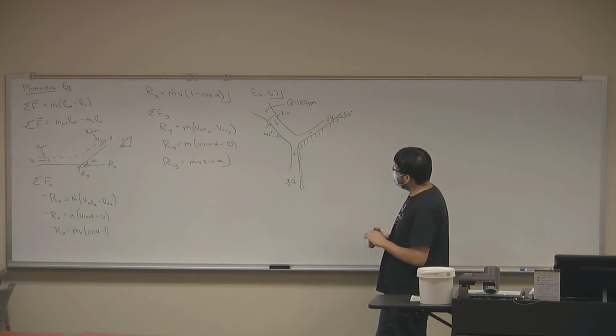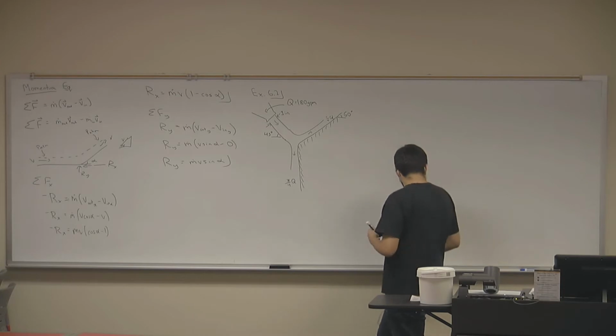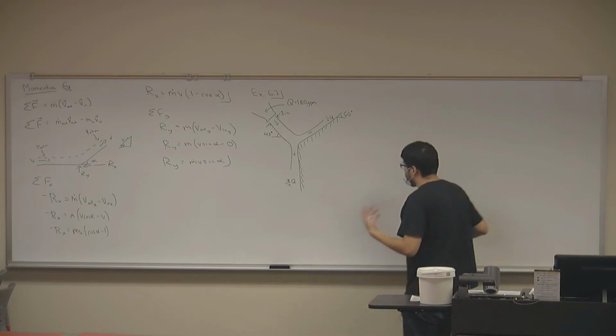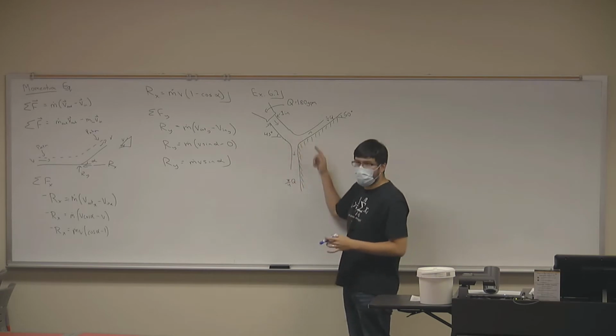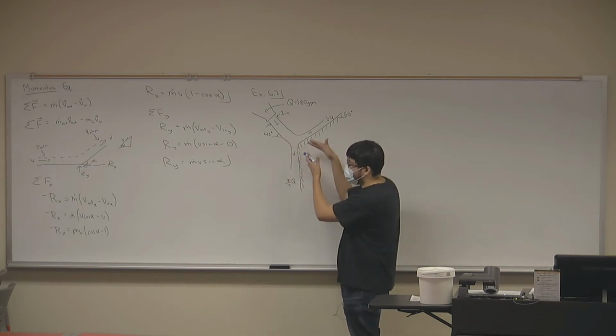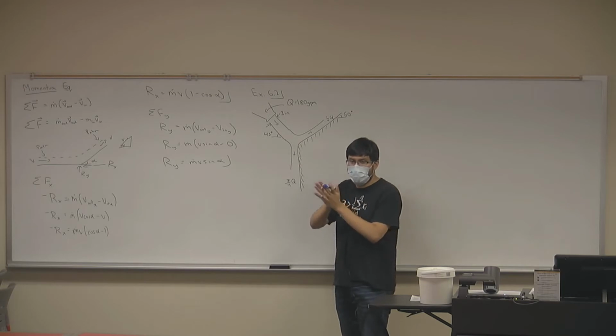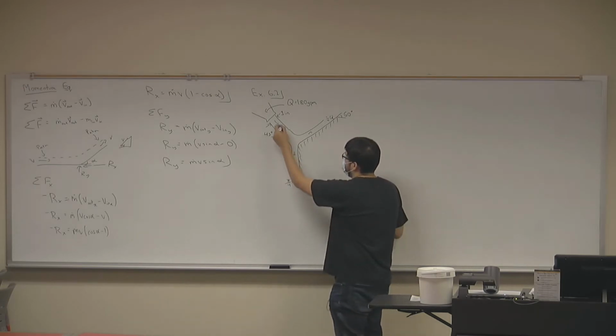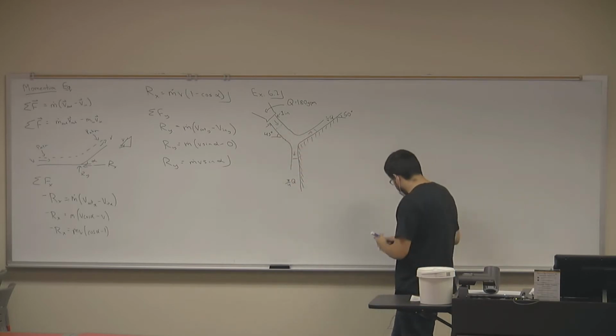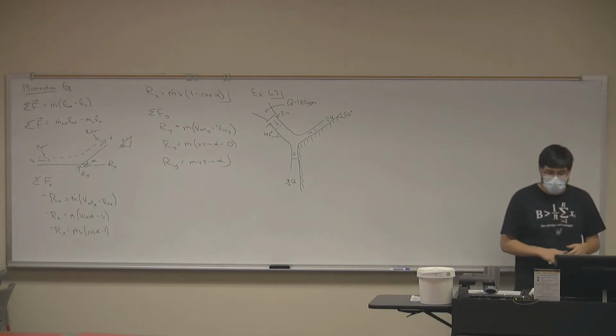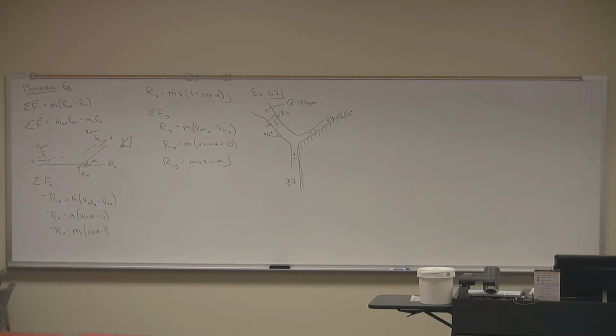We can select our control volume, and just by looking at the diagram, I would recommend that we select our control volume before the deflection, because then we can account for any exchange of momentum that occurs when the water changes direction. So we can select our control volume to be just before the deflection and end just after the deflection. Now, if this is our control volume, Rami, how many inlets do I have and how many outlets do I have? 1 inlet and 2 outlets. That's correct. Does everybody agree with Rami? 1 inlet and 2 outlets. Good.